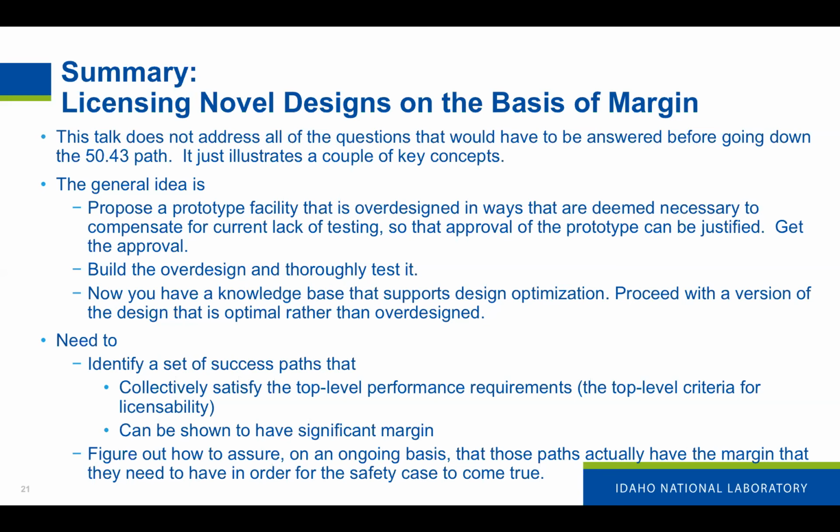And of course, in shutdown operations, if you've got the head off and people are in containment and so forth, you want to maintain decay heat removal in such a way that the core is not threatened. And somebody proposed setting a temperature criterion such that if it were tripped, then you'd know that you had done something.